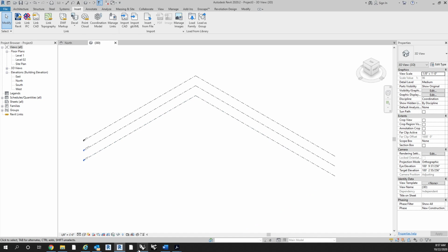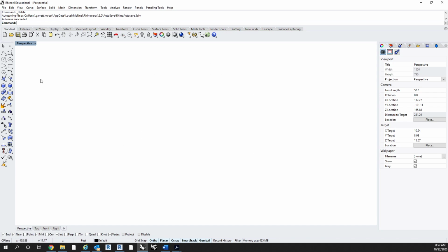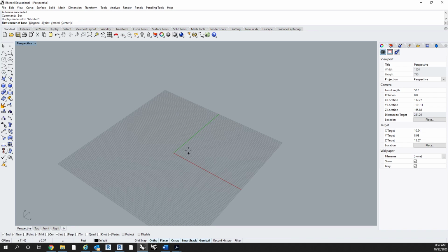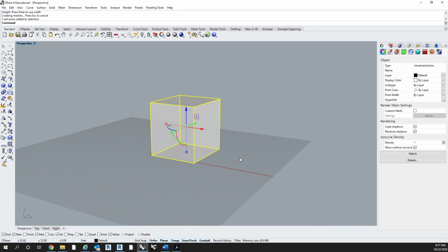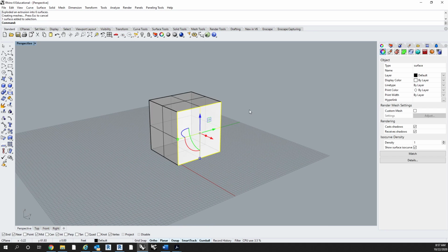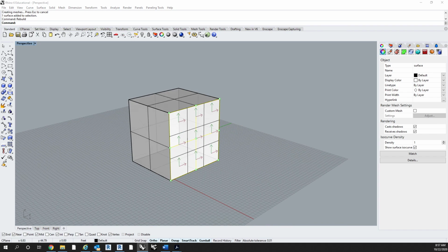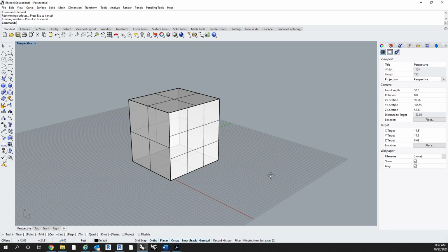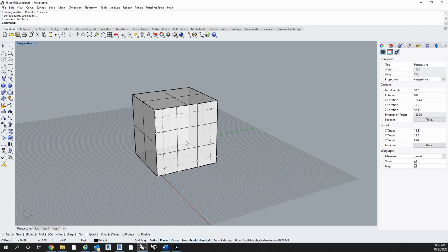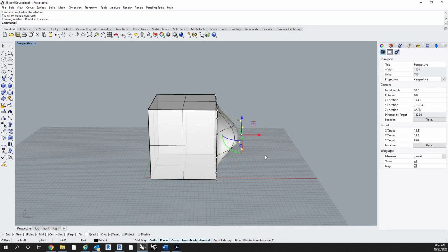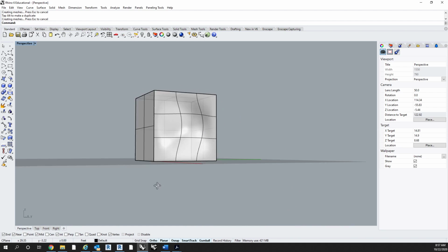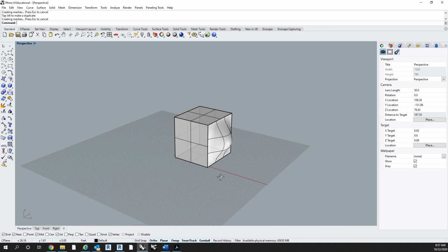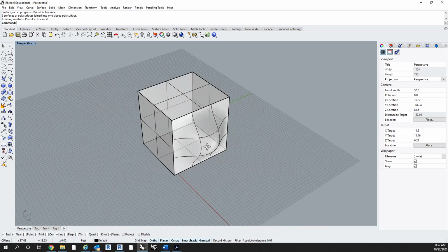Now, obviously, we need to model a geometry. So what we'll do is do a really simple box. And I'll turn on, just so we have some reference. So just do a simple extrusion. You can do it any way you want. I'm going to explode this guy for right now. I'm going to take one surface, I'm going to rebuild it. Hit OK. And then I'm going to do points on and take these four central points. I know I moved through that fast, but hopefully you guys are proficient in Rhino from comp methods. And I'm just going to create a weird bump, essentially, in this file. And then I'll select everything, join it again, so it's a solid.